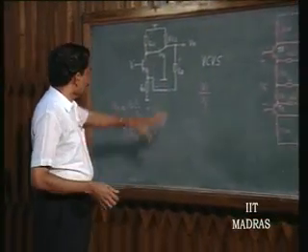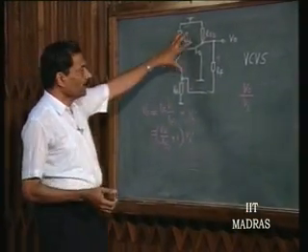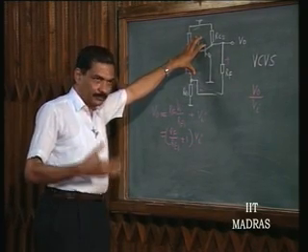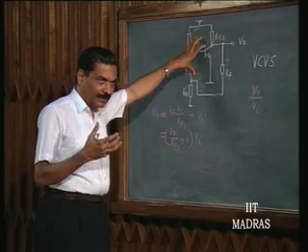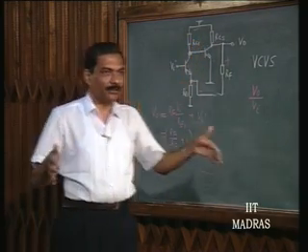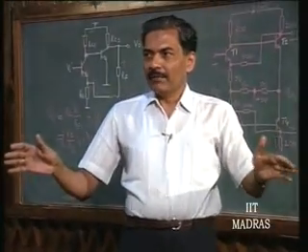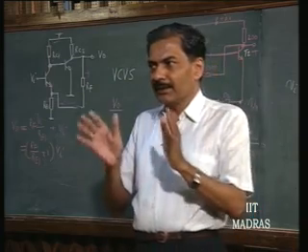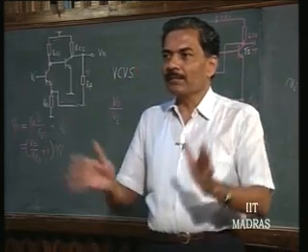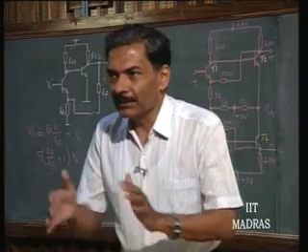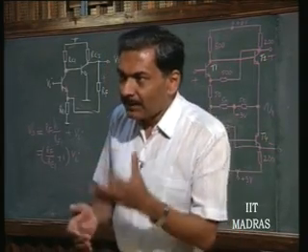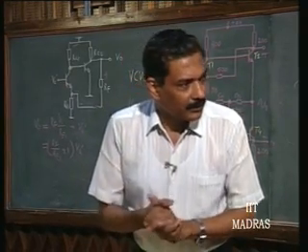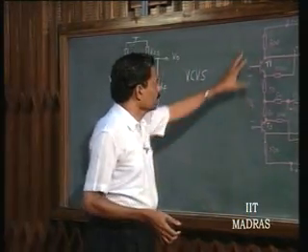Now, if I would like to fabricate this as an IC, I want to make my job of biasing easy. Then I can convert this into what? The basic principle is differential mode, right. By converting every discrete circuit configuration into differential mode, you are getting over the problem of stable biasing, that otherwise would have required level shifting and also bypass capacitors, etc. So, this is what is tried here.